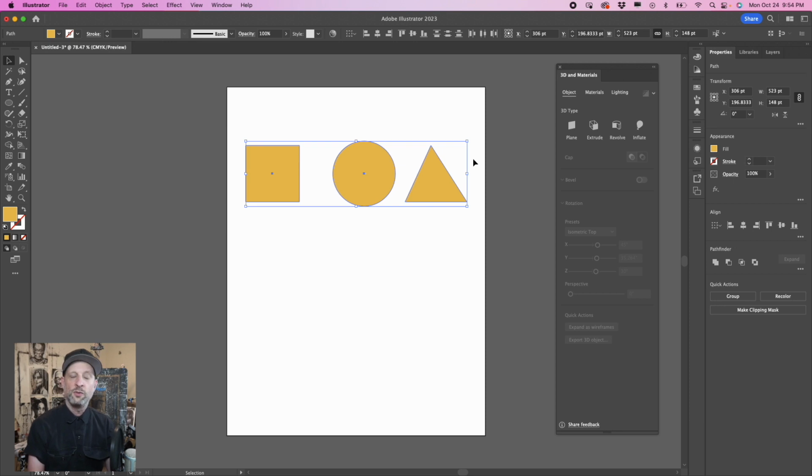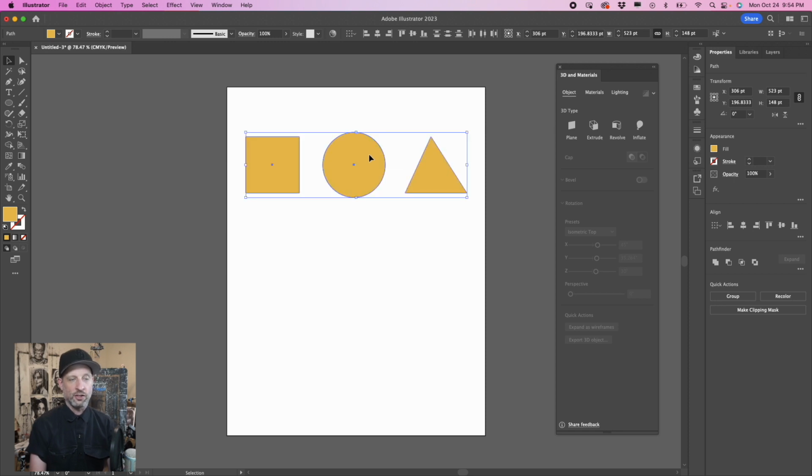And then let's also space them out evenly. So let's go to the three dots, which will open up more of them. The distribution is what we want to do. We want to distribute horizontally centered. So let's click that. Now they're all evenly spaced out, and that's a good thing. So that's a lineup. Now you've learned a little bit about the alignment tool while we did this as well.